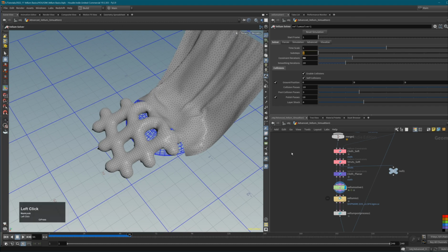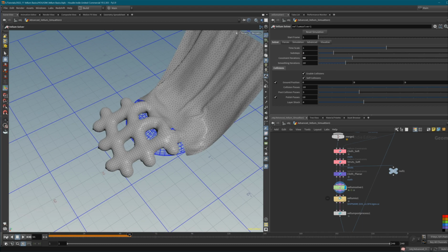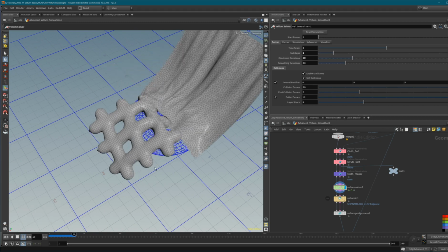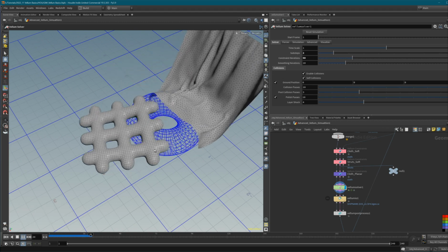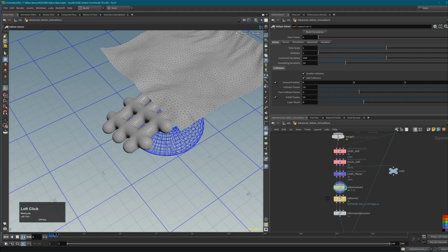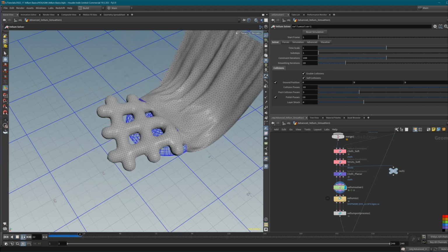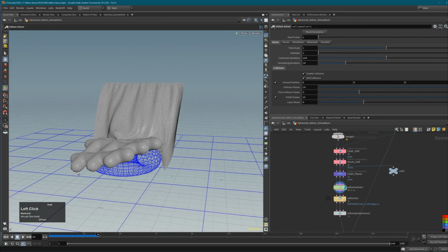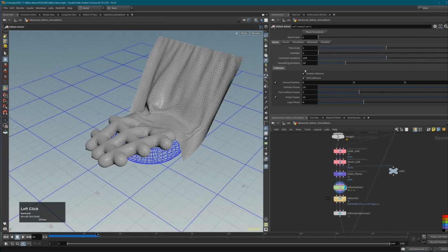And if you now increase the substeps, this will calculate these 50 constraints 2 times. So we again have altogether 100 constraint iterations, but now they are calculated in 2 steps. So this is also not very good. In this case, it's really better to leave the substeps at 1, increase the constraint iterations, and then we get more or less a nice result. If I take a close look now, I have some problems with these struts here. They are poking out a little bit, as you can see here.